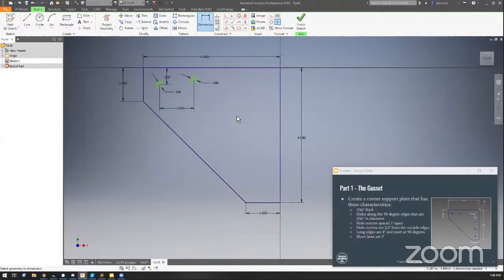If ever you're going down a route like this, you've got to be thinking, there's got to be a better way. And there is. I don't know if it's the best way, but it's the way that I do it. So what I'm going to do here is undo all that, and grab our friendly construction line and put it across here. Now I'm going to bring this horizontal, so you see the implied horizontal constraint that's going to be applied there. Select that, and now I've placed this whole line.